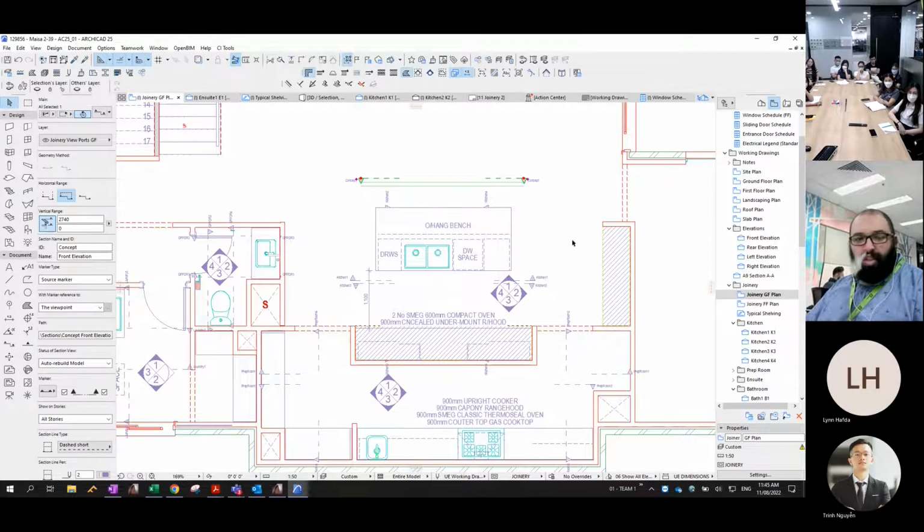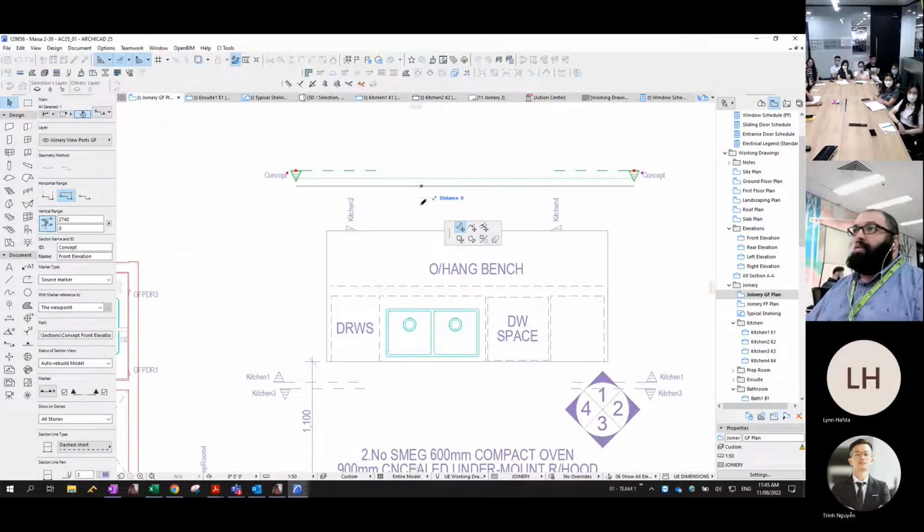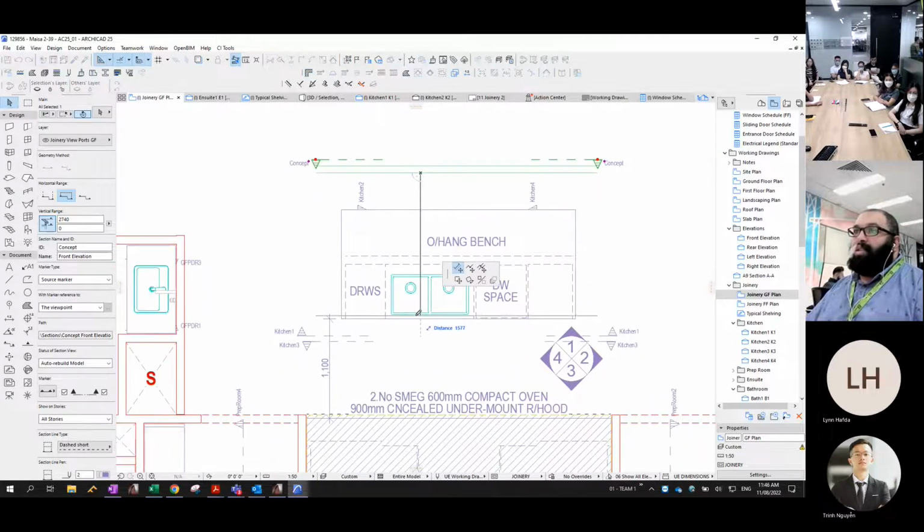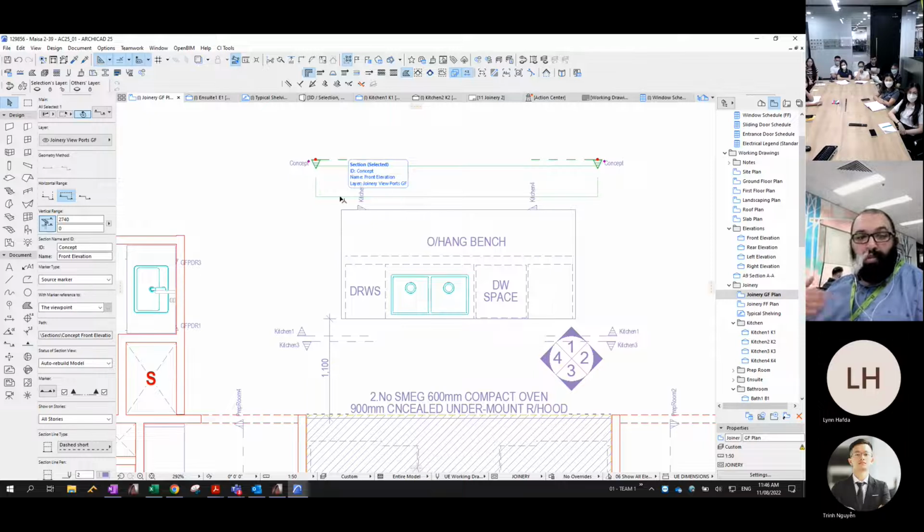If you find that it disappears like the one that we were doing, you'll just need to turn on hide your layers so that you can actually see the viewport. This is the extent of our viewport, which we can see behind it.